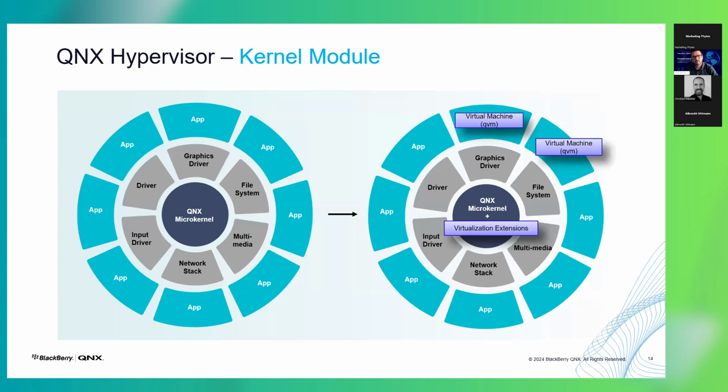So when you look at this slide, on the left is the QNX RTOS: MMU protected memory space for spatial separation, priority-based real-time scheduling, SMP support, and all these security features. What we have done is we've added a virtualization extension to the microkernel. So now it becomes a hypervisor that schedules and isolates whole operating systems. And that's been built by the same QNX team that designed and built the safety microkernel. So the programs that you build initially for that QNX operating system on the left will work exactly the same if you have a hypervisor-enabled system like the one on the right.